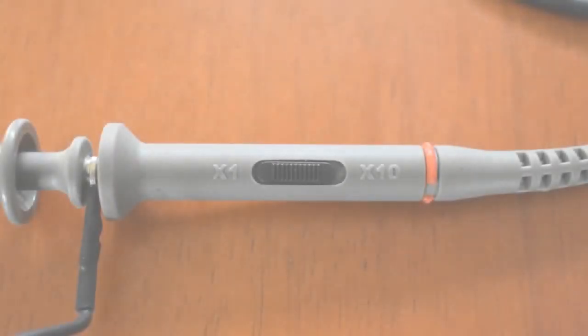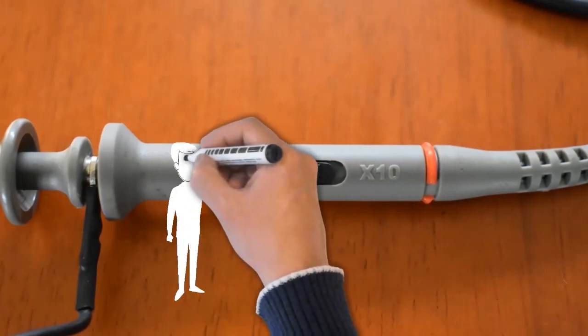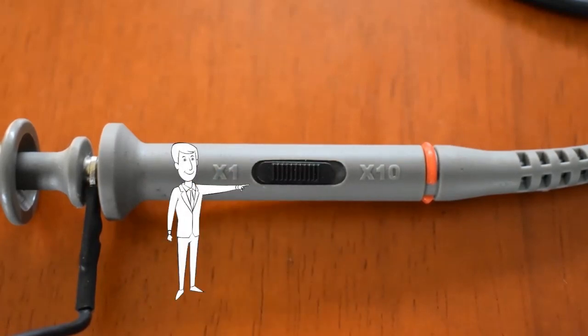If you look at most oscilloscope probes, you will see a little switch labeled 1X on one side and 10X on the other side. This refers to the amount the probe attenuates, that means reduces the amplitude of the signal. If you switch it to 1X, it is exactly like our wire. The tip is connected directly to the inner wire of the coaxial cable of the probe, and the round clip is connected to the shielding. This works well for signals with frequencies less than a few MHz. Coaxial cable can act like a capacitor and add more than 100 picofarad to the test circuit.